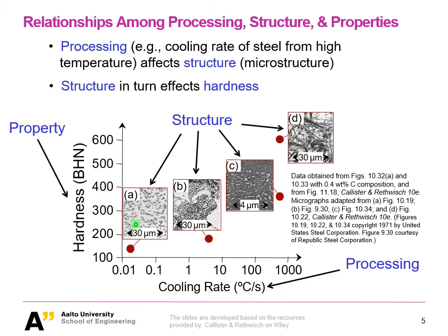Yeah, that is the spheroidizing. What you produce after that is the spheroidite. Yeah. So you have the ferrite, and you have this rather small particle cementite. Yeah, it is very soft. Yeah, and that's why you have rather small hardness value.